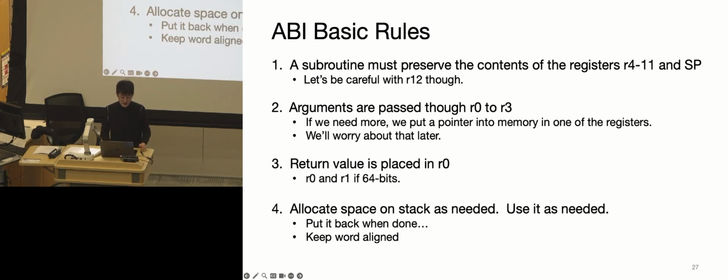One of the more special cases is R12. It's another general purpose register. We covered that in the interrupts. That's also one of the registers that holds some temporary numbers, and it is also caller saved. Basically, it's used a lot of times if you do some more complicated add or multiplication, those are the registers typically used to hold the temporary or intermediate results. So that one is also caller saved. So just one special case on R12.